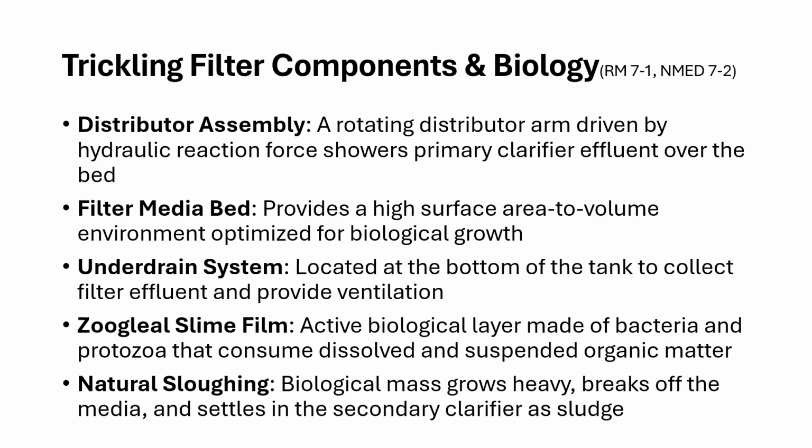We also have an underdrain system at the bottom of the tank, the filter bed, and that's going to collect the filter effluent, and it's also going to allow for ventilation, for air to circulate through that filter bed, thereby giving us aerobic conditions or an oxygen-rich environment for these microbes to metabolize the organic waste.